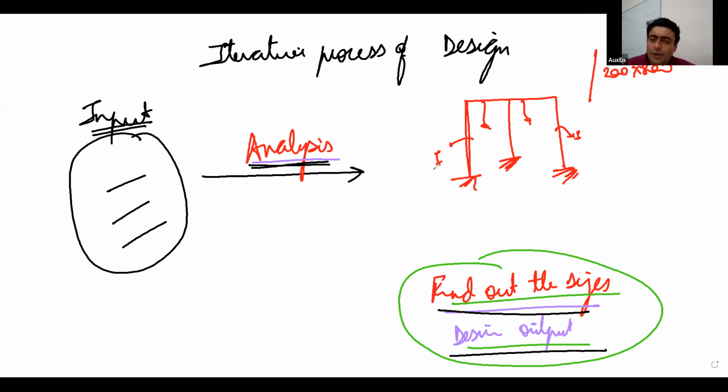So we need to know the moment of inertias, the flexibilities, or the stiffnesses of these sections in order to derive analysis results. Therefore, in indeterminate systems or in systems where there is redundancy, you need to have the section sizes in order to carry out analysis, because a change in section sizes changes the analysis results.